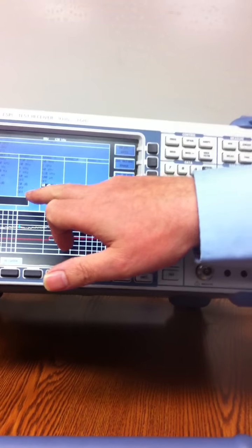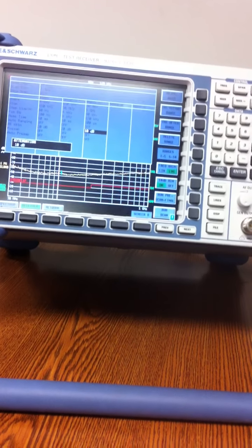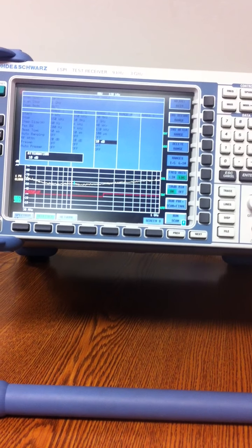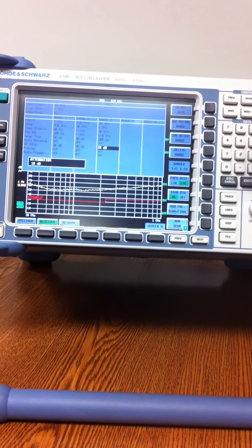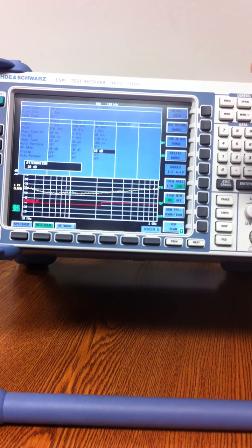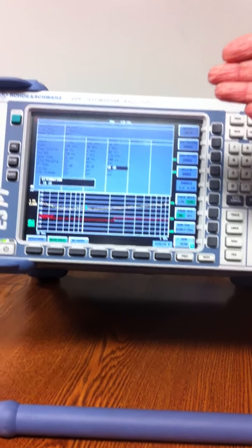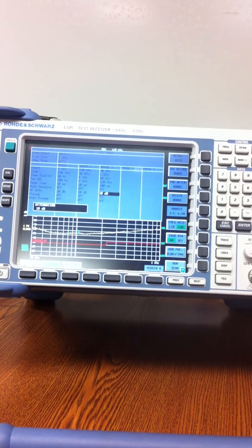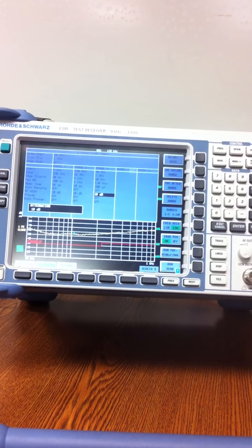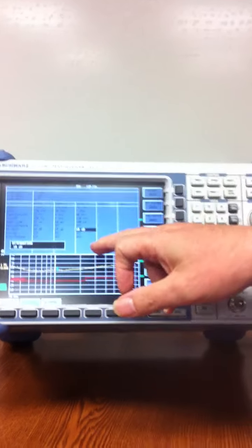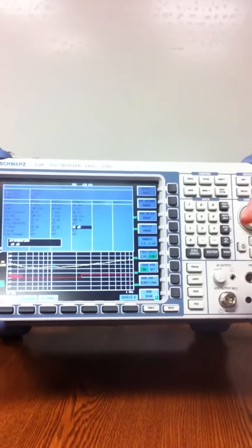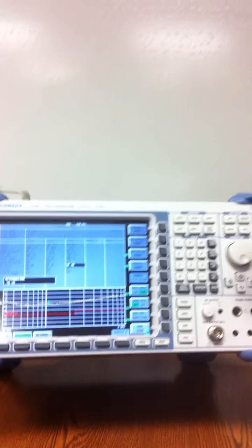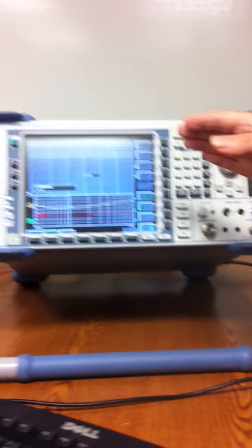For the conducted measurement, 20 dB is a good value, because if you pick up some high values for the EMI, then the overload will not come up. If you put 10 dB in here, that will happen very often. So it gives you a wrong idea of the level of high EMI if the light comes up and there's some overload in the system. So you have to play with all those numbers.